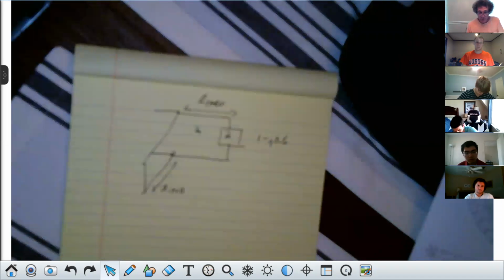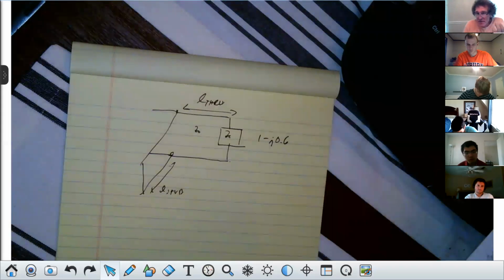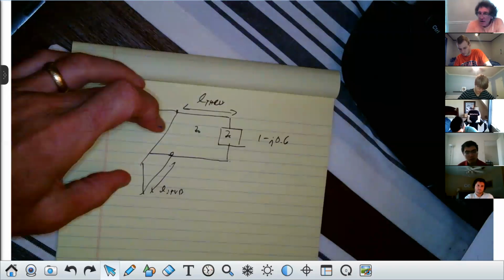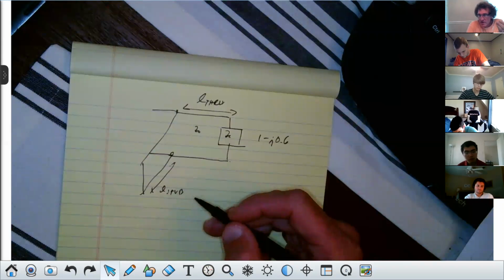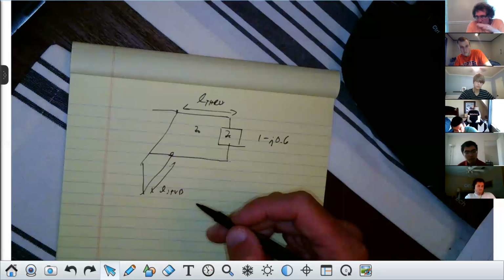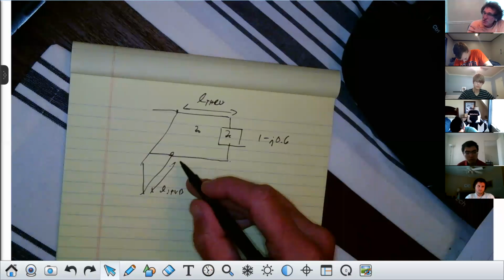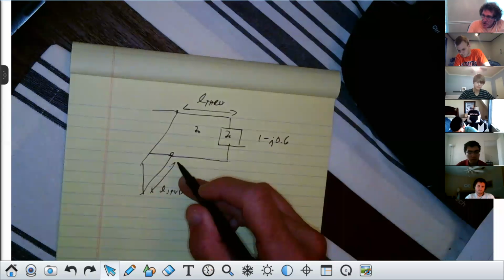Now listen, this is important. If I wanted the stub length to be minimal, and that's typically true for a reason. When we're talking about fabricating stub tuning like this, instead of using an element, you always think about the real estate you're going to need to do that. They talk about the footprint of your circuit a lot of times. So if you have a piece of silicon, and this is going to be fabbed on, say, using a coplanar line or something like this, something very small, where these chips are going to be small, if this line is long, it's using more of the actual surface area of the silicon. Make sense to everybody? You don't want that.